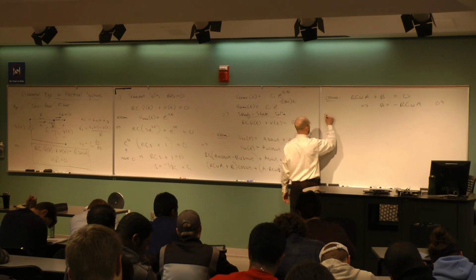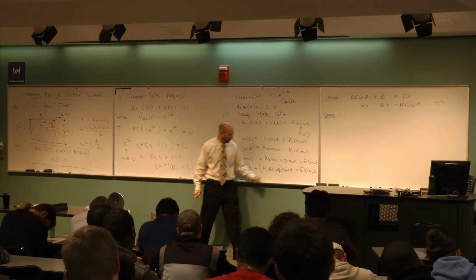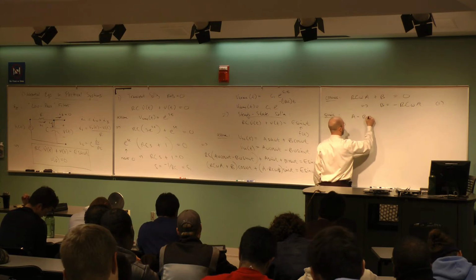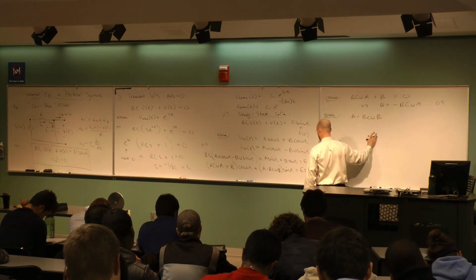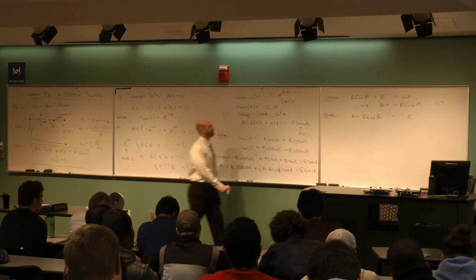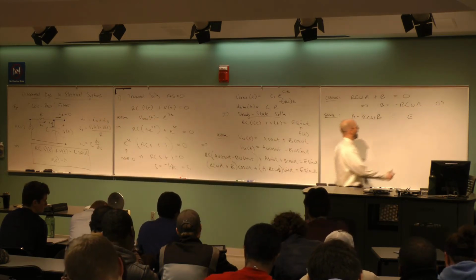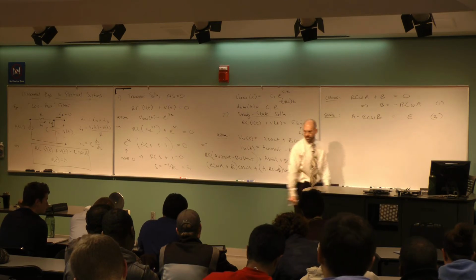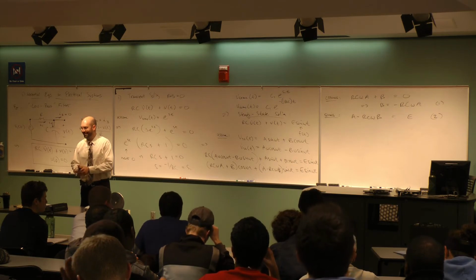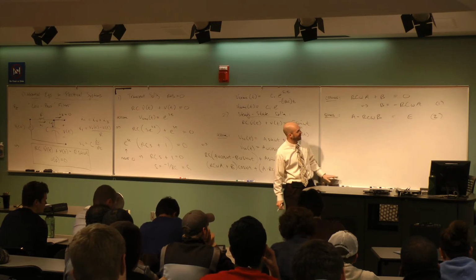So that's one thing. Call that equation 1. And then if I look at the sines, whatever's in front of the sine on the left has to be the same as whatever's in front of the sine on the right. So don't I get A minus RC omega times B? And that would have to be the same as the coefficient on the right, which is E. So that's equation 2. Now, both of these have two unknowns. We can go back to two equations, two unknowns. We could use the matrix method, or I could do what? Yeah, brute force substitution at this point makes sense to me.